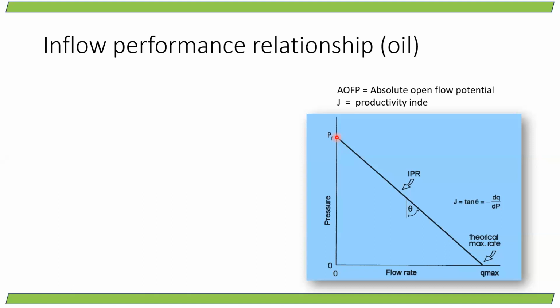Before that, ideally every well should have an IPR constructed. Why? Because if you have the IPR of a well, you can decide the best adjustments, like if you are changing tubing size or flow rate, to give you the best production. This is the reason why we measure IPR. Not only that, it will also tell you about impurities or problems. Imagine if plugging is there, if water saturation is high, or if gas is coming into your well in place of oil. That can also be estimated through IPR.